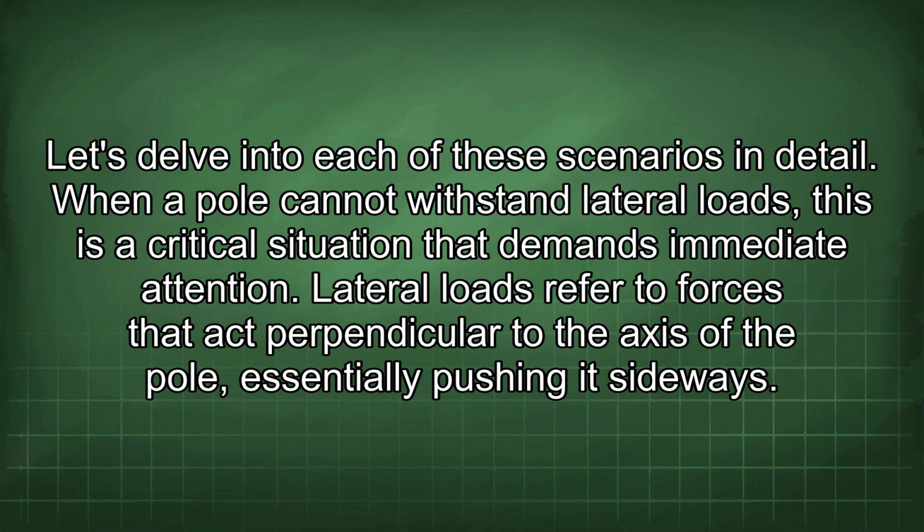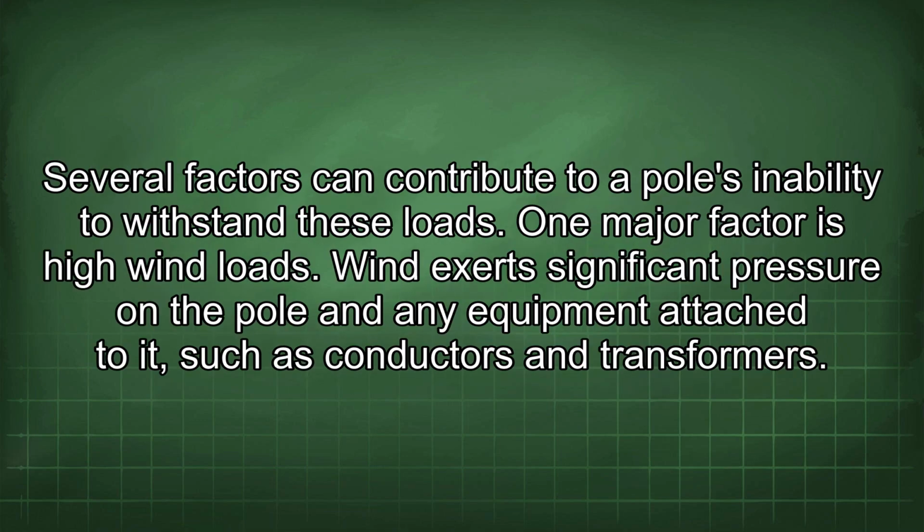When a pole cannot withstand lateral loads, this is a critical situation that demands immediate attention. Lateral loads refer to forces that act perpendicular to the axis of the pole, essentially pushing it sideways. Several factors can contribute to a pole's inability to withstand these loads. One major factor is high wind loads. Wind exerts significant pressure on the pole and any equipment attached to it, such as conductors and transformers.